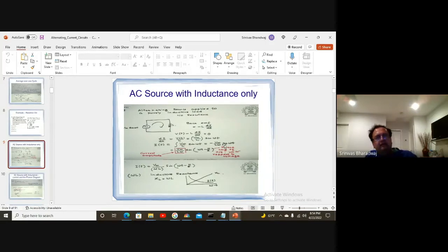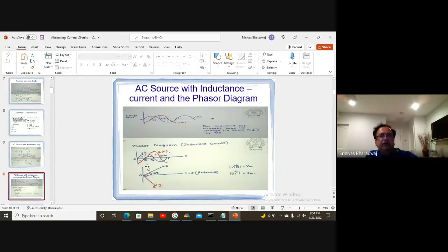So in the phasor diagram, if this is the voltage, the current will be 90 degrees behind it. So it is a lagging current. Look at this picture. Remember this picture. This is a pure inductance. Okay. So with this picture, you will see a lagging current. So this is a very important idea that you should learn to be comfortable with.